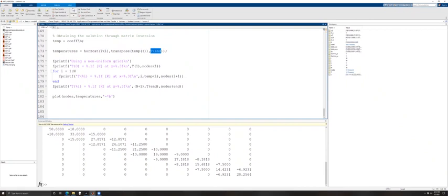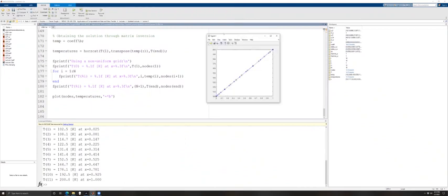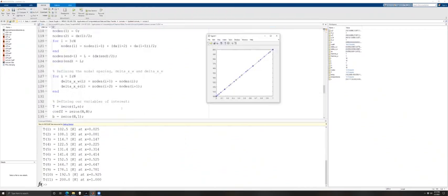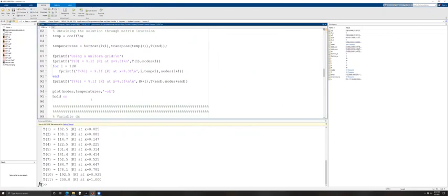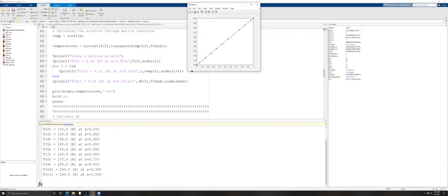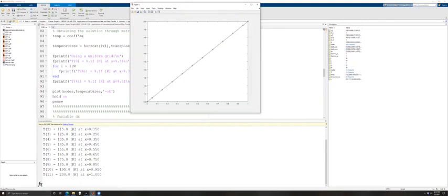And what we're going to do is click the run button, and we're going to take a look at this. Now, the first part of the code, we had a constant dx. We've already looked at the solution, and we know it makes sense because we definitely have a linear temperature profile, but we saw these circles right here are representing the cell centers of our 10 control volumes. And you can see they are equally spaced.